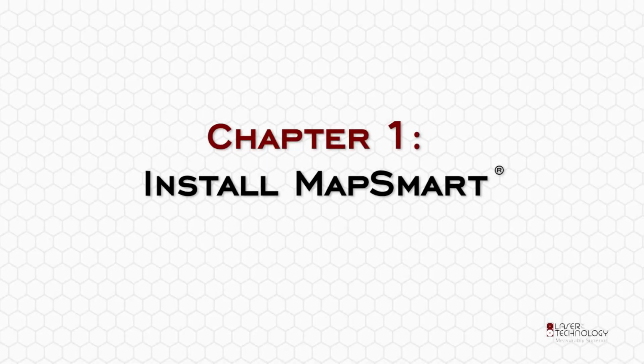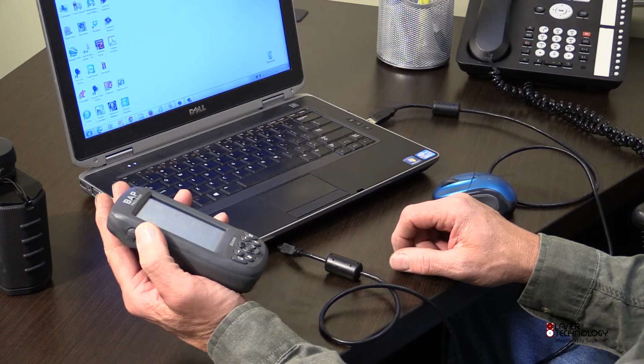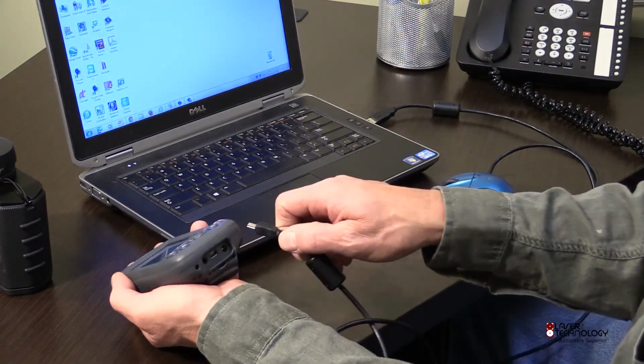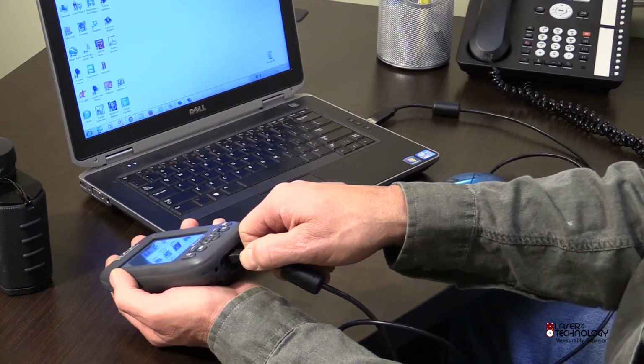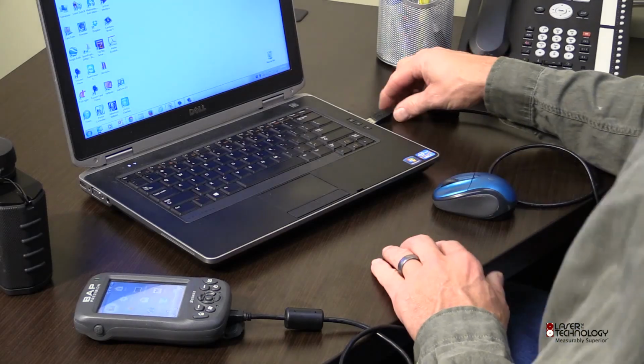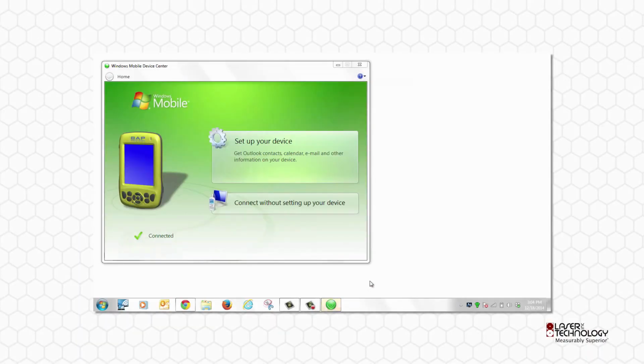Chapter 1. Install MapSmart. Begin by powering up your data collector and connecting it to your PC. Establish communication between the two by inserting the micro USB end into the bottom of the data collector and the other USB end into your PC. Windows Mobile Device Center will launch.